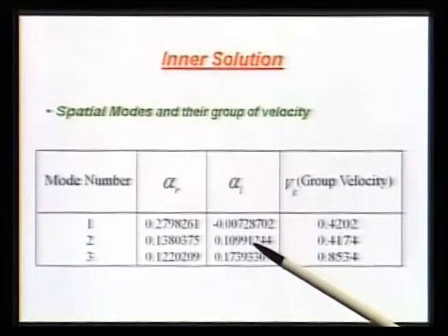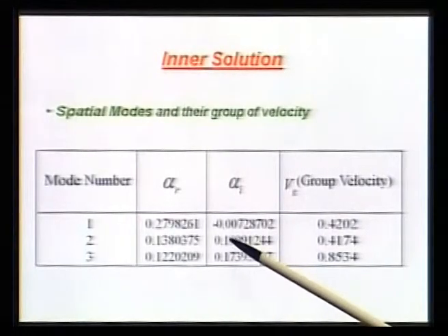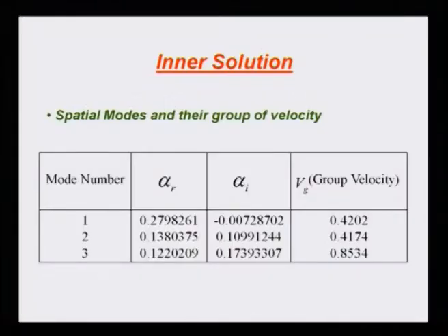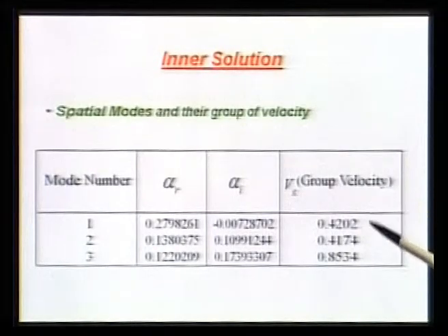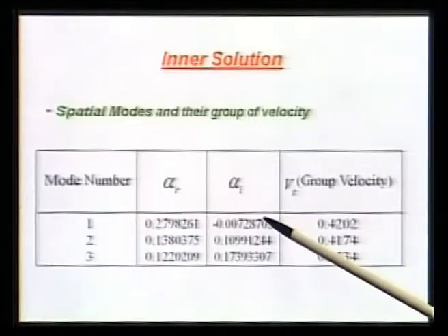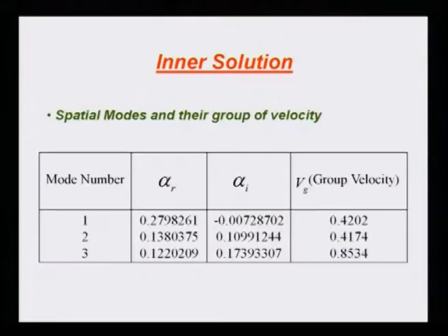These eigenvalues, the last 2, as you can see, come with a plus sign. So, if they were going downstream, they are stable modes. How do you find out which way they are going? Calculate the group velocity, and we calculated the group velocities. All of them are positive. So, they are all downstream propagating waves, and then this is an unstable wave, and these 2 are stable waves.